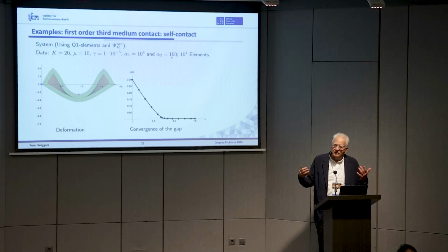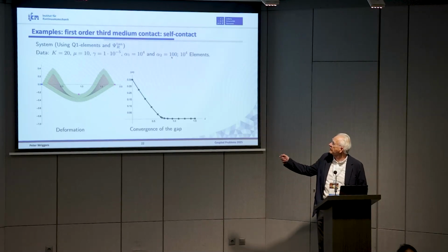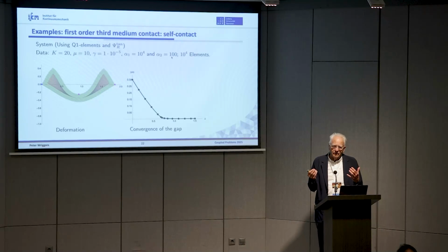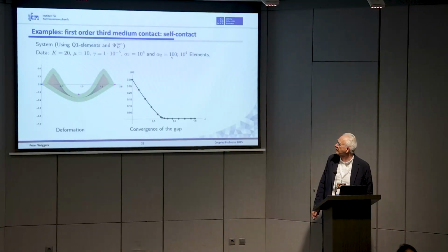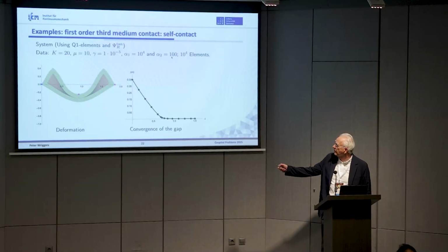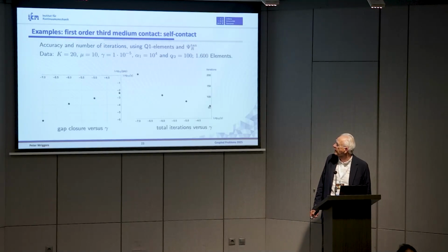I could have done less. It does depend on the element size. But it's interesting that if you take more elements, you still get solutions. Sometimes the fewer elements you take, the more robust your solution is. But here it still works. So you can see here for this problem we get a nice convergence of the gap.